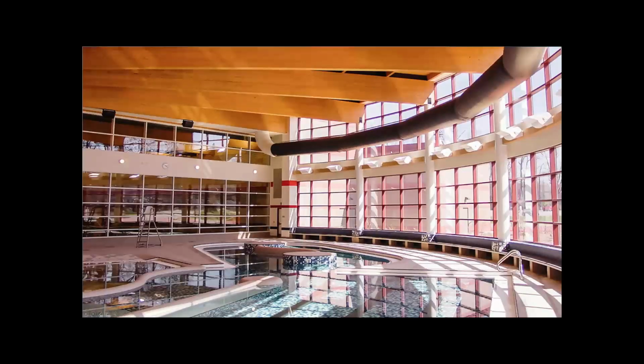Here's another great example, which is a combined application. Over here in the wall, we have linear vents, something like a Price linear bar diffuser, that is just throwing air up the wall. But say in cooling, you're throwing this air out of the DuctSox at the pool area instead. So you could have both. It works really well for any type of high bay application where you have a mixed system.